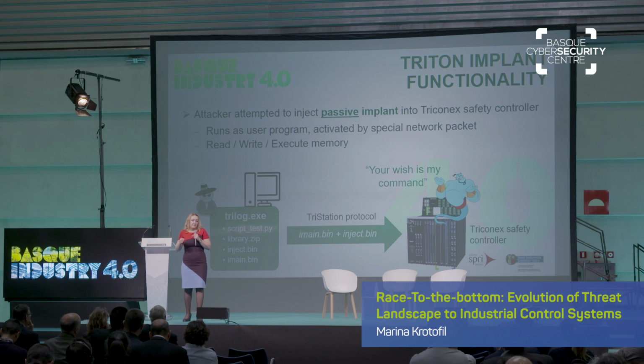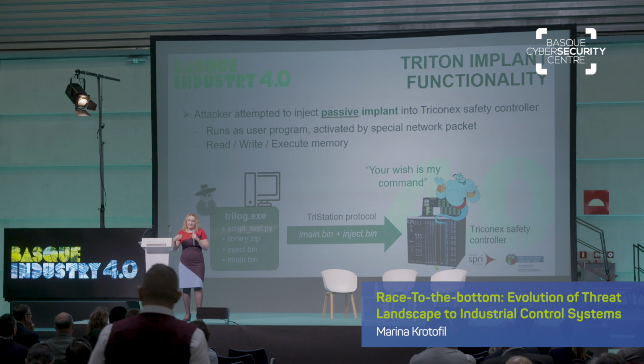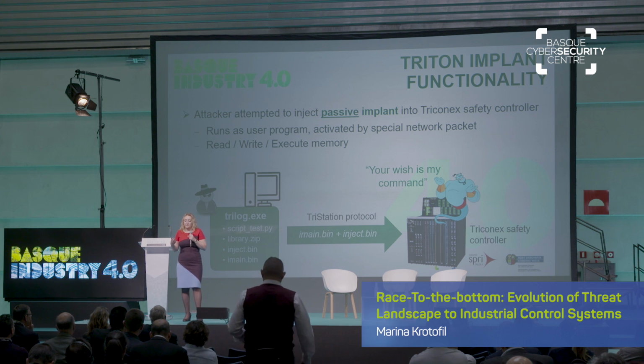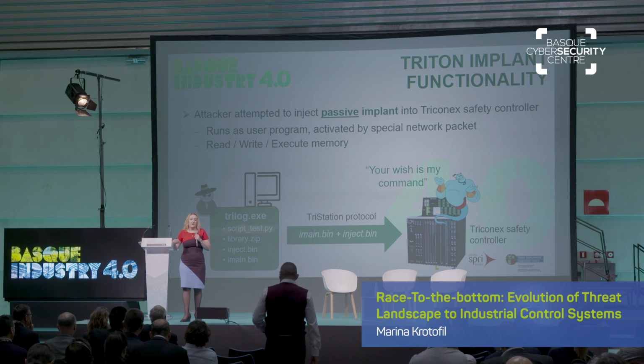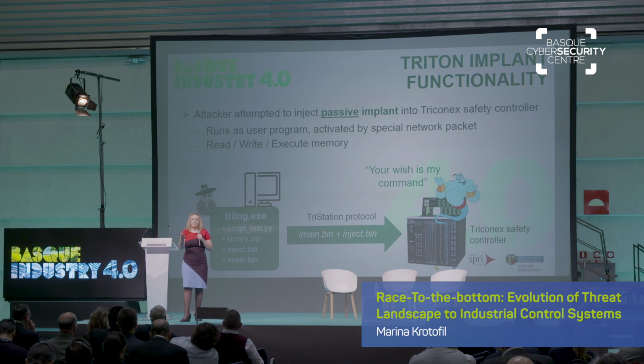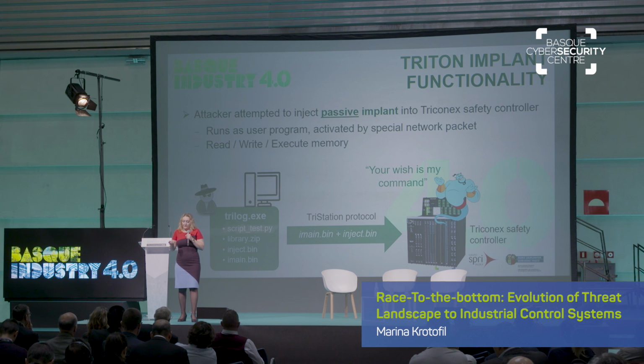What does passive implant mean? It means that this code, if injected, actually does nothing. It's a remote access Trojan. It just sits there in the memory and waits for further commands. So the Triton implant can read, write, or execute memory. For example, if the attacker later wants to bring the damage payload, they will bring a code, the Triton implant will write it into the memory and then later execute it. Basically, with Triton, the safety controller becomes a slave.